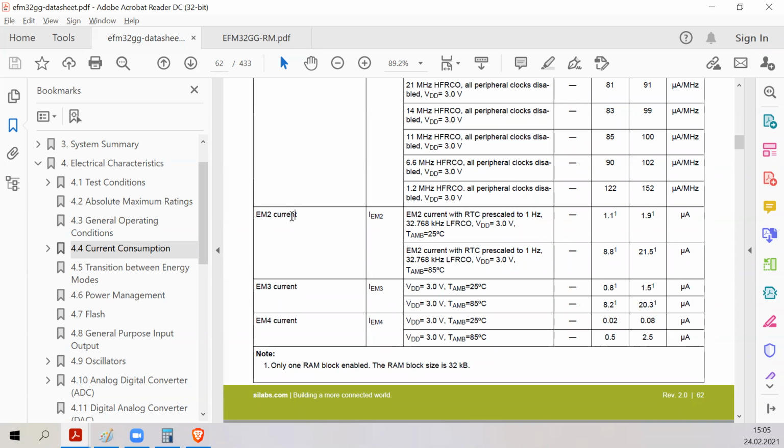However, if you check out energy mode current in the next line, you might ask, well, what is this 21 microamp? The problem is that, as you know, when silicon is heated up, it has more ionized electrons, so it has a leakage current. So even though all the field effect transistors are closed, there is some leakage current that flows through the microcontroller, even when it's not doing anything.